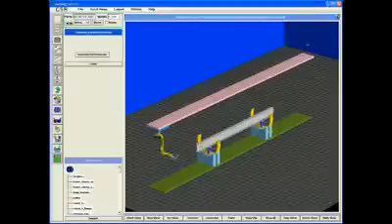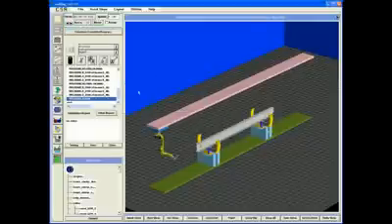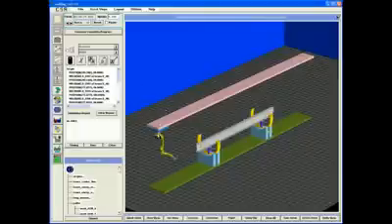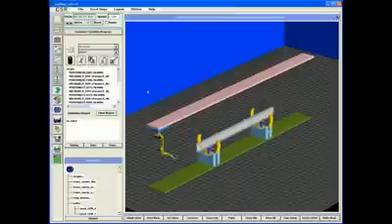Go to the Generate Program icon in the toolbar and simply click Generate Part Program. What you see here is a very high-level representation of the welding process. We've got positioning commands that slide the robot horizontally along the rail and also rotate this assembly clamp so that the weld can be performed.